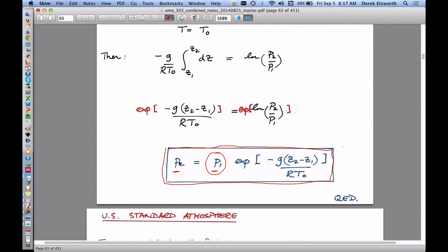An implicit assumption in that, though, if you remember, is that when we wrote this, we didn't write the temperature inside the integral. So implicitly, we assumed that the density was changing only as a function of pressure, and therefore an implicit assumption was that as you go up in the atmosphere, the temperature remains the same. So at sea level, it's 20 degrees centigrade. At 10,000 meters on top of Everest, it's also 20 degrees centigrade, which typically is not the case. We know that just heuristically.